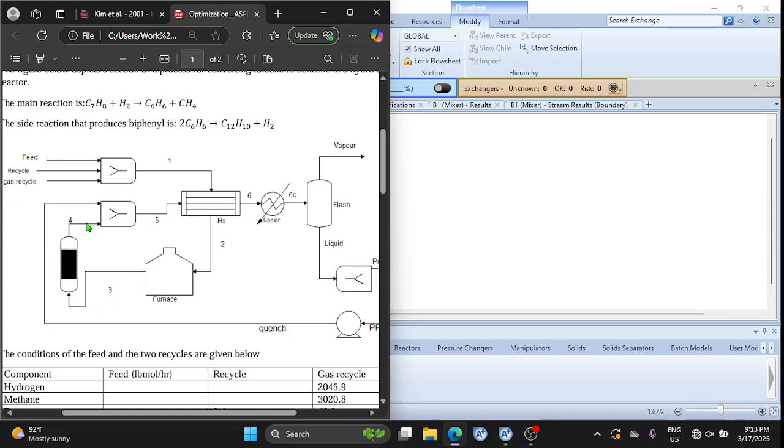What's coming out of the furnace would be the hot stream, and what's coming into the furnace would be the cold stream. So I'm just trying to heat up what is coming into the furnace before it gets into the furnace, right? Because it doesn't make sense that what is coming in, I try to cool it before I heat it up again. It makes more sense to heat it up a bit before I heat it up with the furnace so that I use less energy. So if we think about this economically, maybe I have a stream, it's at 20 degrees Celsius, but I need to heat it to 500 degrees Celsius to place into my reactor.